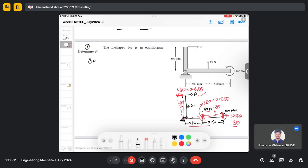So from the principle, the summation of all the virtual work will be 0, and the work can be given as F times 0.6 del theta. This is the 60 Newton force, and we have a virtual displacement of 0.5 del theta here, so 60 times 0.5 del theta. The moment will create work as well, which is the moment multiplied by the angular displacement.